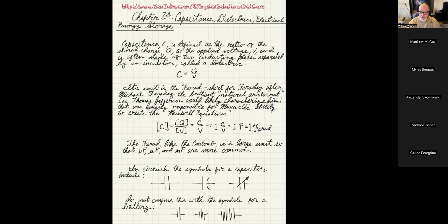Unlike a resistor, where you can just flip it around and connect what was the right to the left and what was the left to the right, in other words the direction of the current going through the resistor doesn't matter. That's often the case with just a plain capacitor, but they've discovered they can make some capacitors better and smaller if they let them be polarized and only be connected in one particular orientation. Those other two symbols are a couple of the symbols used for such capacitors.